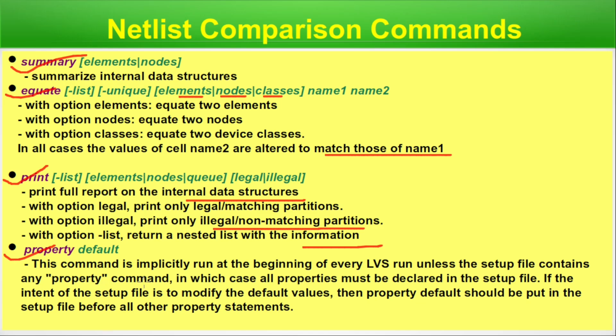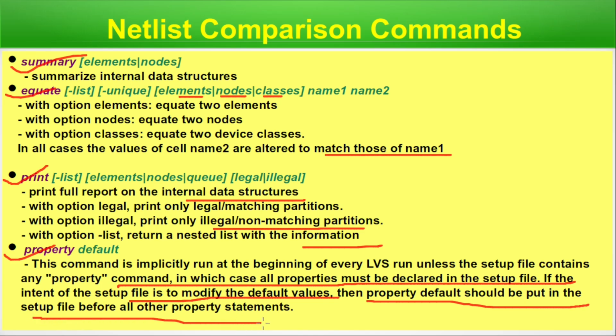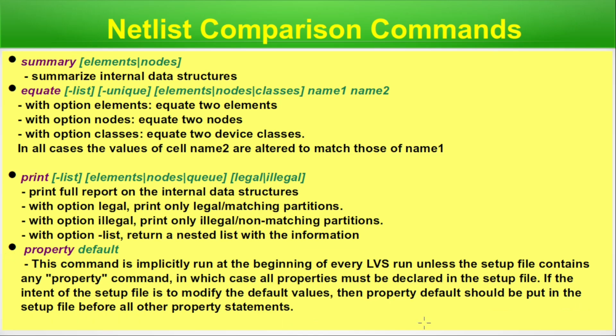Property default. This command is implicitly run at the beginning of every LVS run unless the Setupfile contains any property commands, in which case all properties must be declared in the Setupfile. If the intent of the Setupfile is to modify default values, then property default should be put in the Setupfile before all other properties. So here also we get a reference of Setupfile.